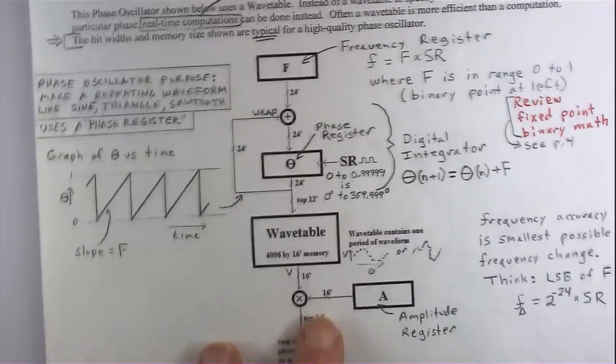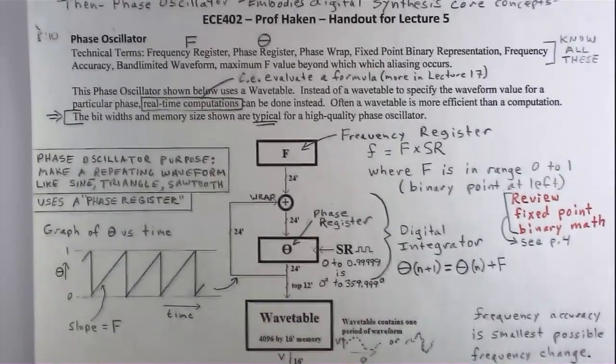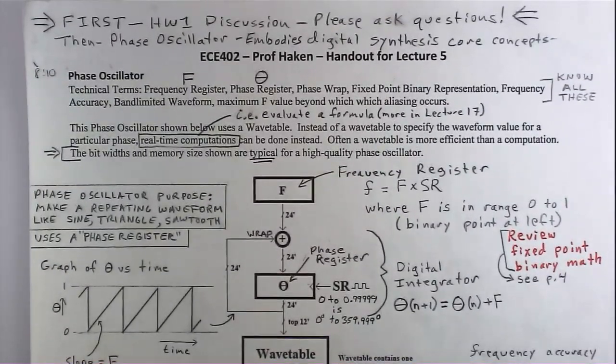So a sine wave is pretty easy because, say, for instance, you want to figure out, well, is this going to alias? Well, it's really easy. You just don't play a sine wave that's over the half sample rate. Just ignore it. And if it's below the half sample rate, you play it. That's really cool. But now let's say you have a more complicated waveform like the sawtooth.